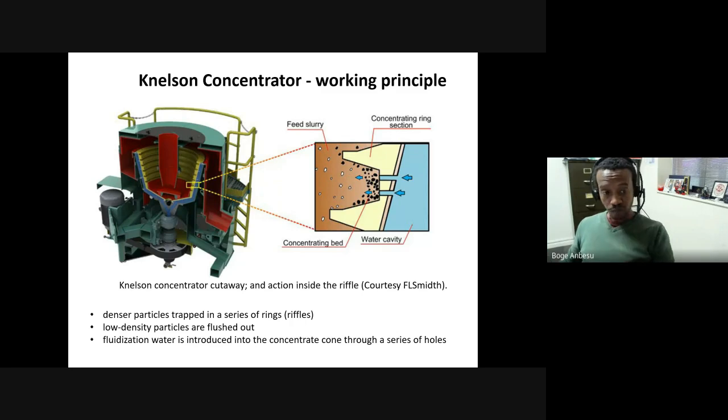In any case, one of the important factors here is, as I said, the fluidization water to prevent light particles from separating out with the dense particles. This is just to allow only the dense particles to come and concentrate in that riffle.